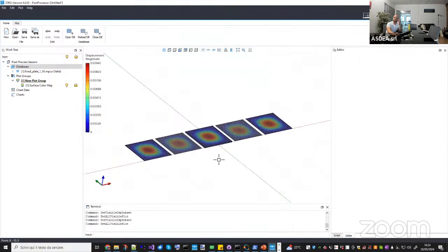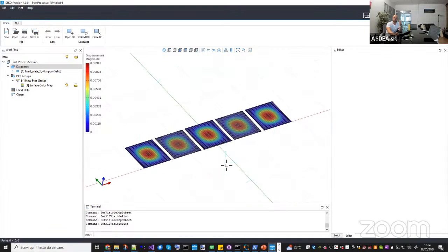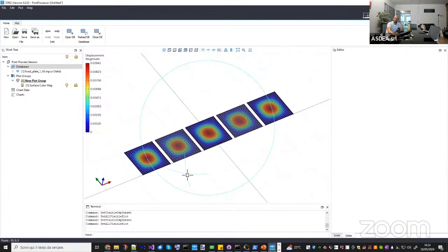So the point is, why do we need these? I mean, we can always use the thick shell element at this point. And I can say yes. So basically, I always use thick elements because they perform well both in the thick case and also in the thin limit, okay? So you may ask, why do we have these formulations in OpenSees, but also in other software? It's basically for historical reasons.